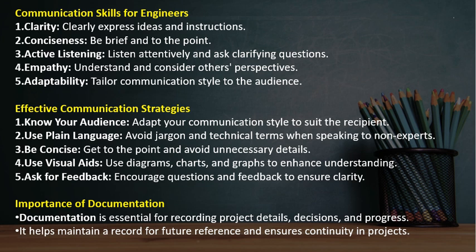Somebody comes after 5 years and he wants to work on the same location. How would he know where the water pipeline is? You have to look at the records, right? In the documents. And this is, by the way, a requirement for every project. You have to get the approval from the ministry, the housing, for your design. When they get your design, they will look at their records. So you are saying, I will do excavation 10 meters. At 10 meters, there are electricity line and water pipeline. They will not give you the approval. Got my point? So documentation is very important, even for future work as well.